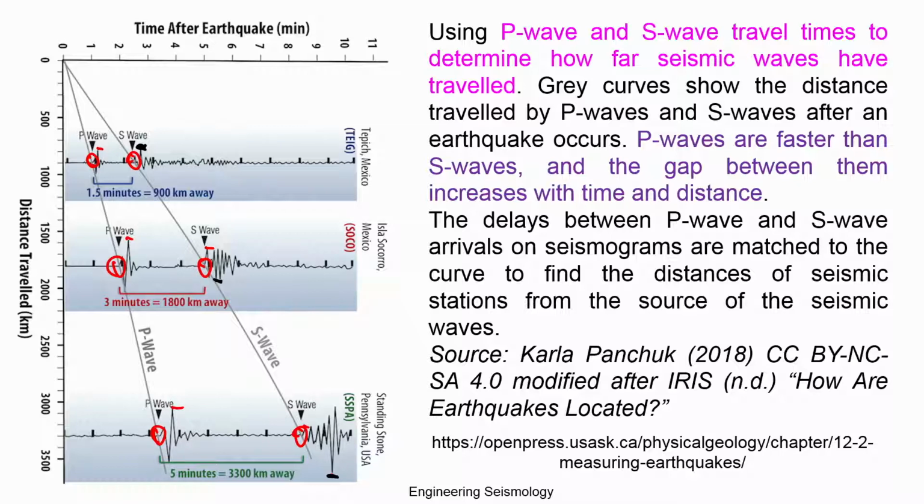Second, the amplitude. For the P and S waves, generally the P wave we do not consider as an amplitude required for the peak ground velocity or displacement part; only the S wave part we consider. Generally the P wave will be lower than the S wave amplitude. So, you can see here this amplitude, this amplitude, this amplitude.